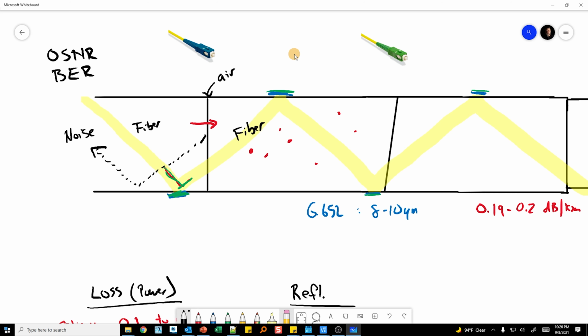There's going to be reflection intrinsically within the glass, right? But after a certain distance, it just flattens out. So it might start at, say, 80 dB of optical return loss, which is span reflection. And as the fiber gets longer and longer, it generally starts to flatten out somewhere in the mid-30s up until infinity. So intrinsically from the glass, you shouldn't get any worse than, say, the mid-30s or in that range.